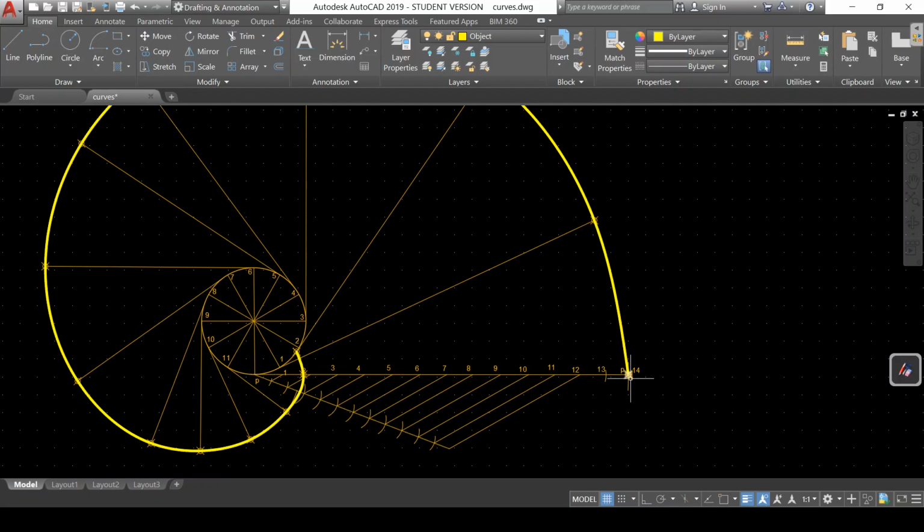So we have marked that at 215 mm. This is by mistake I have written P here. P is not here. P is here initially at the end of the string. So this distance is from this circle, it is 215 mm. And then at every point on the circle we have drawn tangents and then transfer the distances up to P on those tangents. Okay, that is similar to the previous sums. Only difference here is that P is not ending at 12th division. It is more than the circumference.